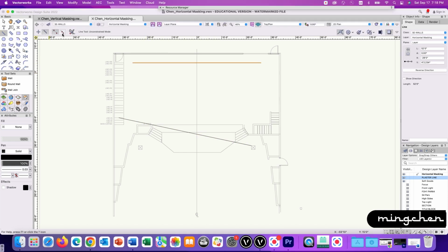Draw a vertical reference line starting at the corner of the proscenium arch located on the stage right. Extend the line to cyc and make the second click. This is the line marking onstage border of all the legs located on stage right. You are now ready to install the legs on stage right.